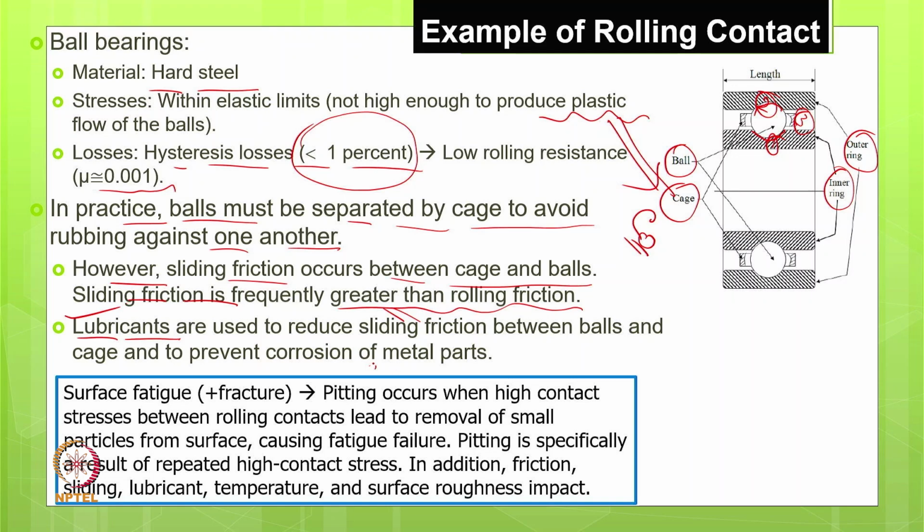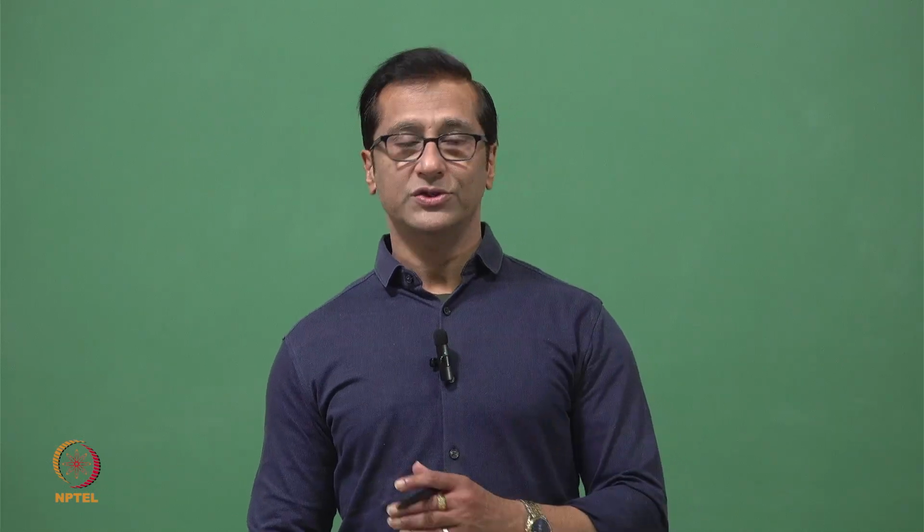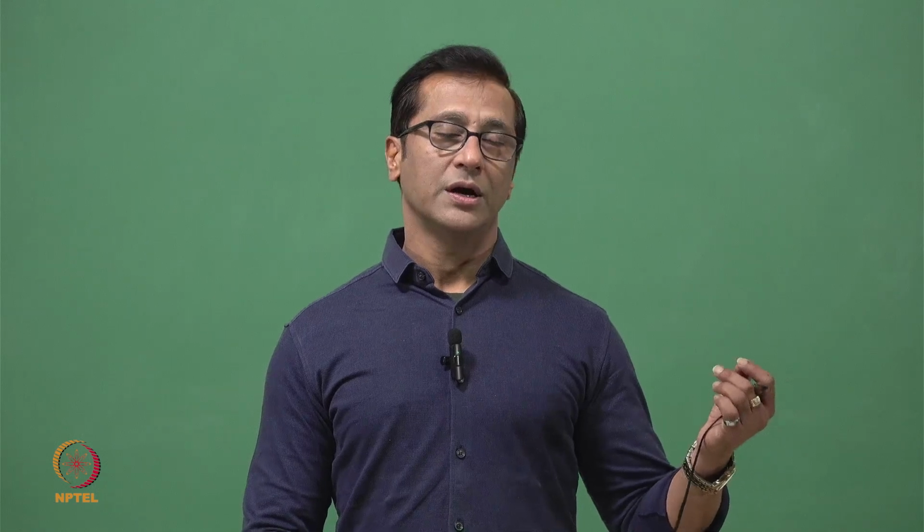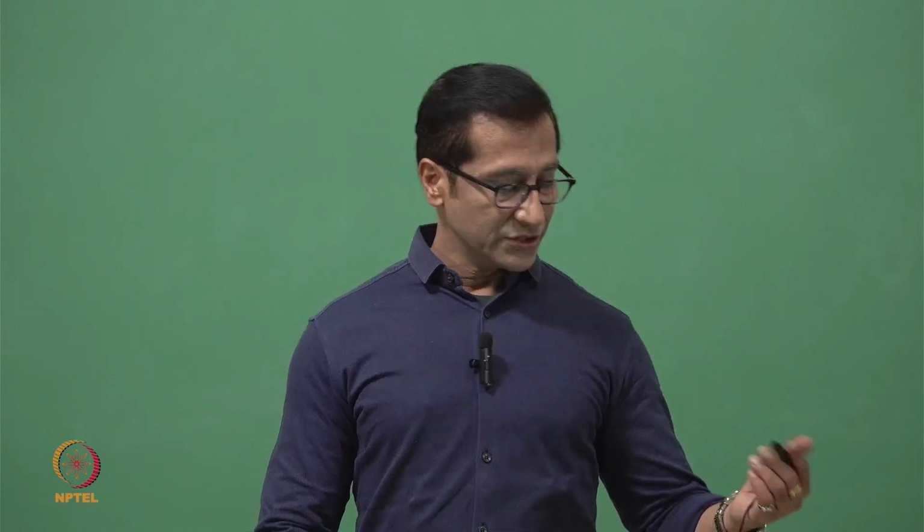In addition, it really provides some sort of protection against corrosion. So, that is also important for us. Now, when we are discussing this topic, we say rolling contact fatigue, and in short, surface fatigue. Whenever we use the mechanism adhesive, then fracture should be added; abrasion, fracture should be added; fatigue, fracture should be added, because finally wear means a separate loose particle, which comes as a third body in this situation.